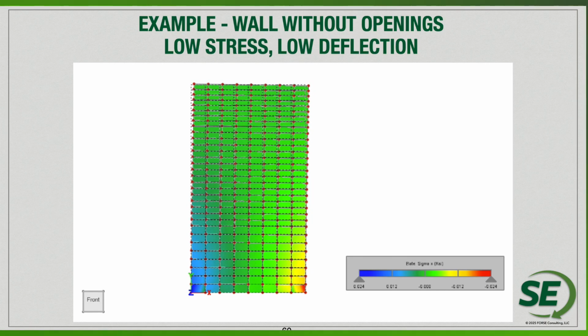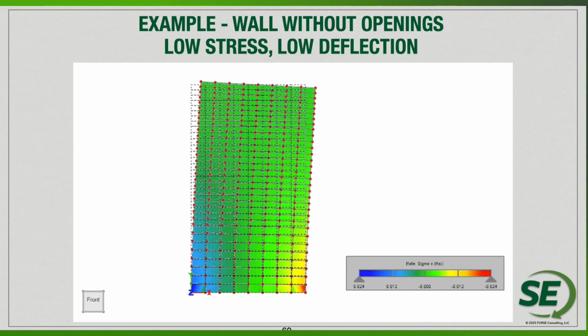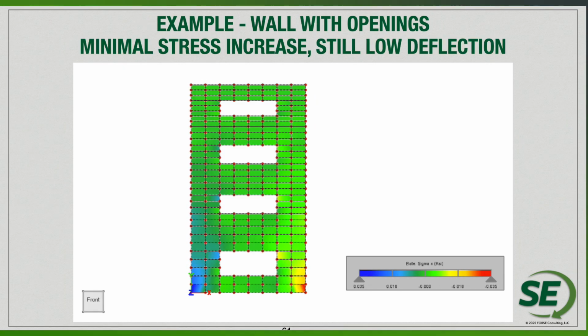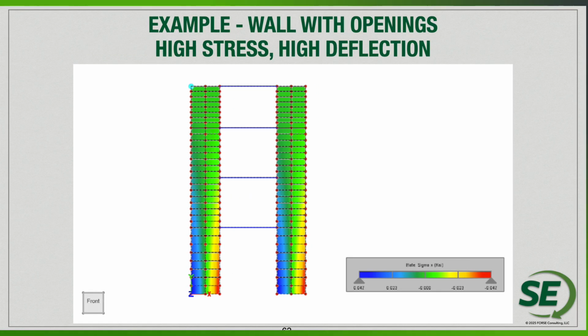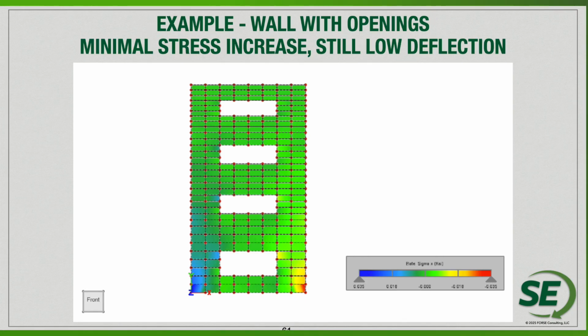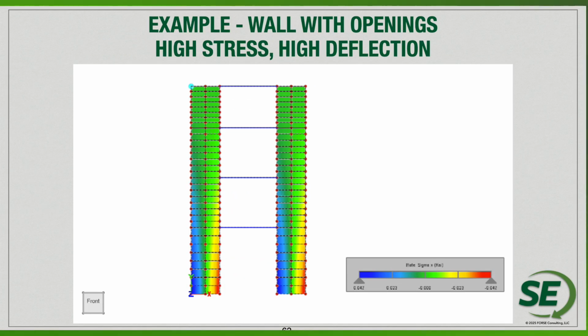So again, just to look at the overall wall performance, we can look at finite element analysis to see what adding in openings does. It really doesn't change the overall stress, the maximum stress areas on these taller walls. You can see that the openings certainly are there, but the stress concentrations aren't that much different. If I start to isolate these elements, you can see actually much higher stress forces in these designs, at least a 50 or 100% increase on the overall stresses.